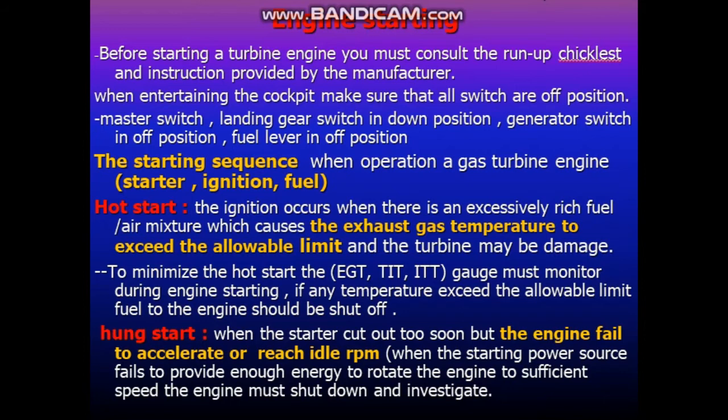That means there is an excess of fuel in the combustion chamber. When you start the engine, the amount of fuel and air is excessive, and that will affect the exhaust gas temperature at the outlet of the combustion chamber. And we will see this video and the effect of hot start.